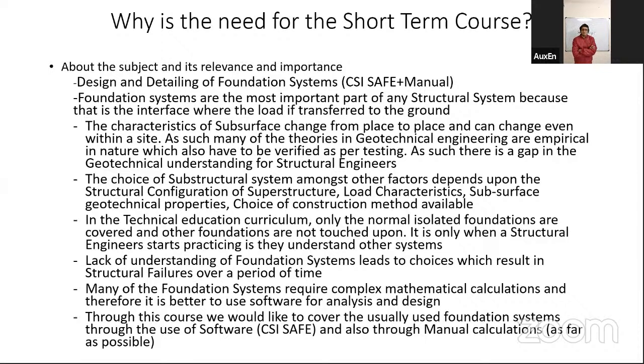Large variations you can observe. So basically, geotechnical engineering, you can say that it is not a perfect science. For superstructure, you have a perfect science: whatever your concrete strength is, let's say M25, Fe500, you know how much reinforcement you have to calculate, and what is the shear reinforcement that you need. All those things are clear for the superstructure because the formulae and everything is properly known to us.